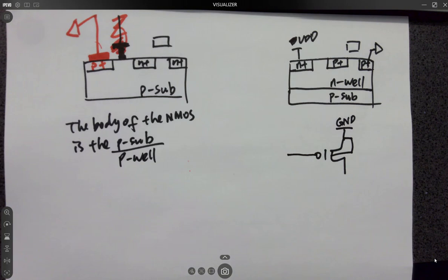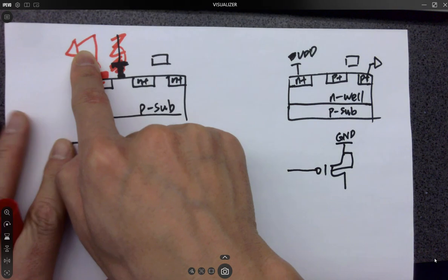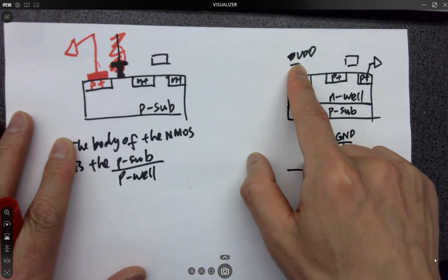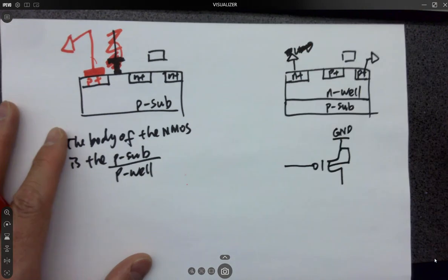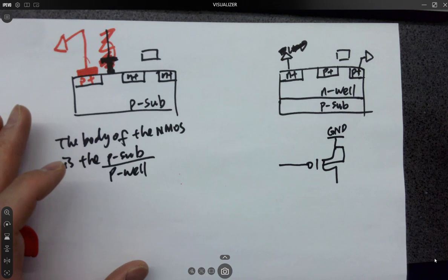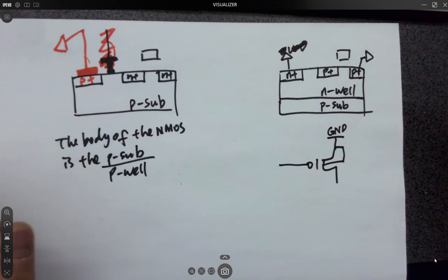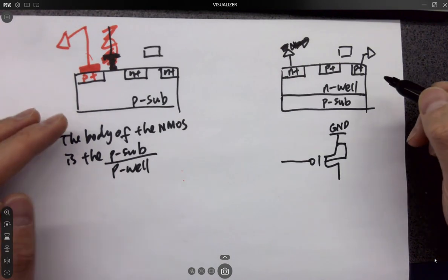I talked about this really quick last time. I'm pretty sure it was a little bit rushed. Let's review this really quick so you are not getting confused for the lab. You short your P plus, the P tap, to ground. Now you are supposed to short your N tap to VDD, but why did you ground it? Can you ground it at all? Can this happen at all?